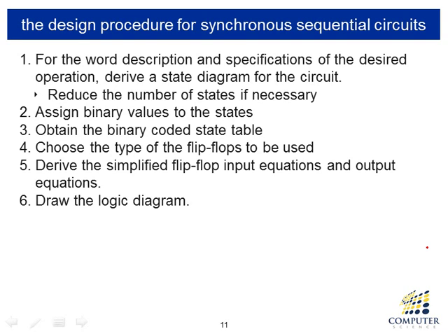Now we are ready to design sequential circuits. Here is the detailed step-by-step procedure for designing sequential circuits. The very first step, from the given description or specification of the system, we derive a state diagram. If possible, we want to come up with the minimal number of states, which obviously requires less hardware. And then out of the state diagram, we assign binary values to each state.